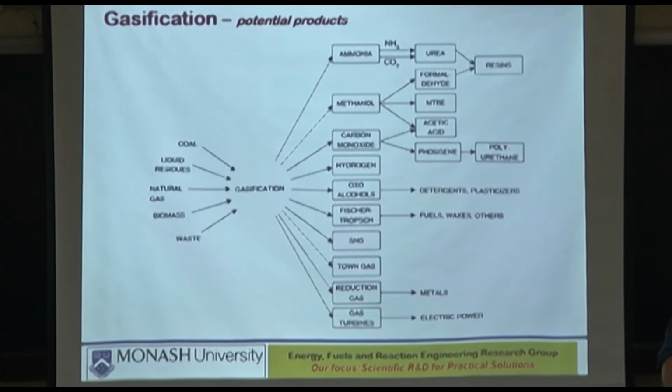If you supply all the substoichiometric air right at the bottom, then the hydrogen, the methane and the carbon monoxide released from the pyrolysis stage will nicely see good food in the form of oxygen near itself. So that is why you have the secondary oxygen, tertiary oxygen, etc., so that it is there where the char is. And when I talk about the different types of gasifiers, I will explain it there. So it's more complicated than what we can think.